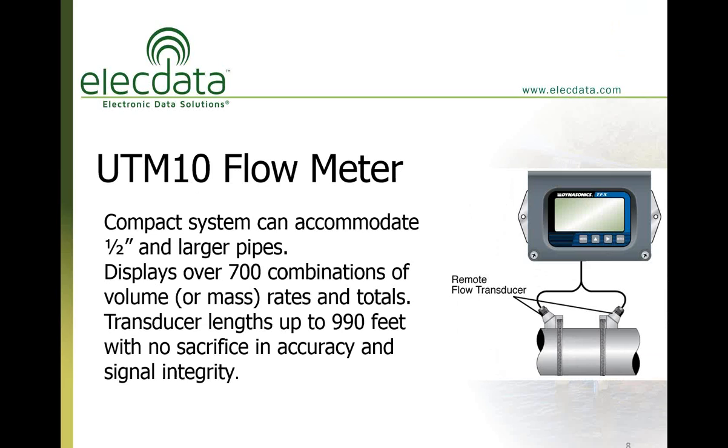The UTM10 flow meter is compact, and as we mentioned, can be installed on pipes 1/2 inch and larger. It can display over 700 combinations of volume, rates, and totals. You can get transducer cable lengths up to 990 feet with no sacrifice in accuracy and signal integrity. So what this is basically getting at is you can have up to 990 feet separation between the sensors and the meter. This is sometimes very common if people want to install the transducers below ground in a vault, yet have the meter/display in a location which makes it easy to see for personnel.